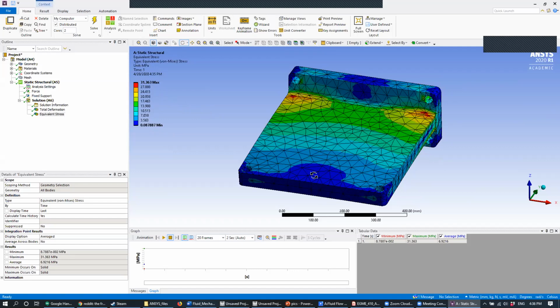Okay. And so what the dark blue is saying is that these regions with very little stress are doing very little in terms of load bearing. So they're basically sitting there, but they're not really doing any work helping to support the load. So it would be nice if we can know which areas we can cut out, which aren't really doing much, to satisfy the same constraints and loads, but save us some material costs. There's a question.